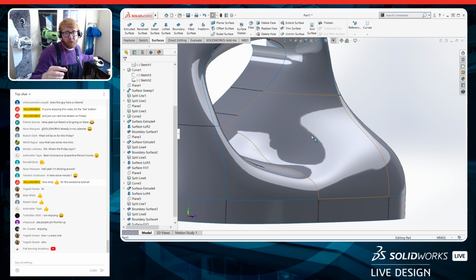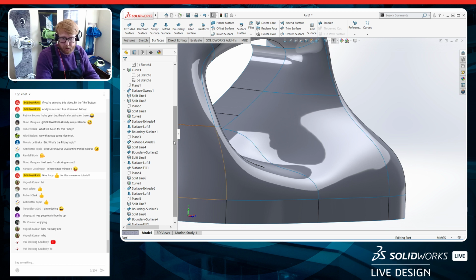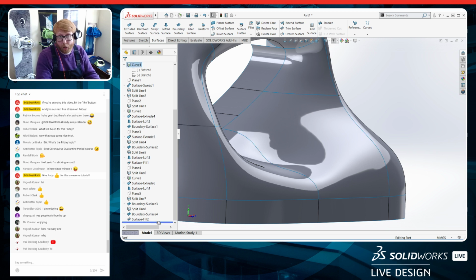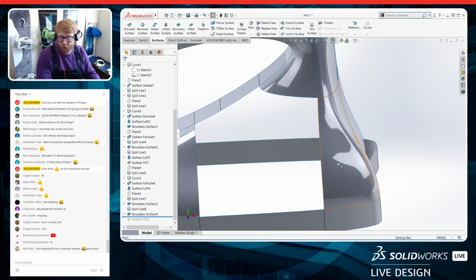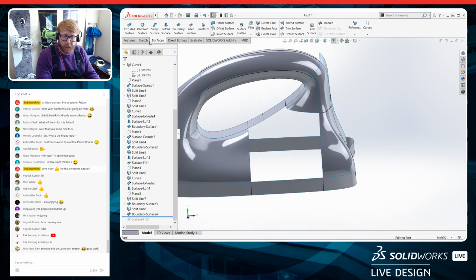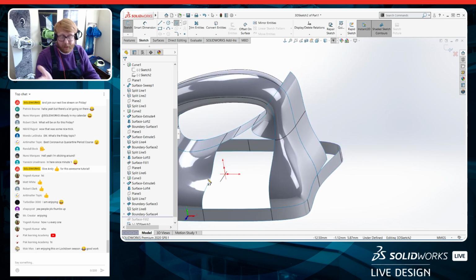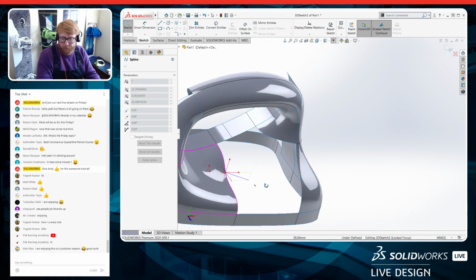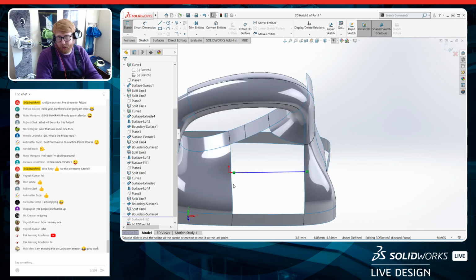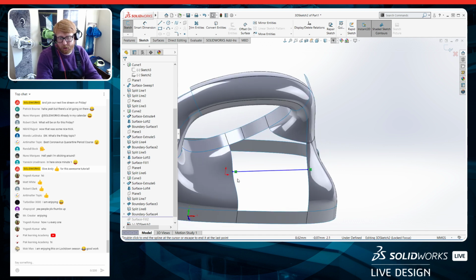So one of the cool things you can do with a filled surface is you can actually add a sketch, or a constraint curve essentially. So I'm going to go back before this, and what I'm going to do is create a 3D spline. Andy, don't ever create a 3D spline. I know, I say that all the time. Never create a 3D spline. It's a terrible idea, right? But if it's just a 2-point spline, if you're just going from here to here, sometimes it's okay.